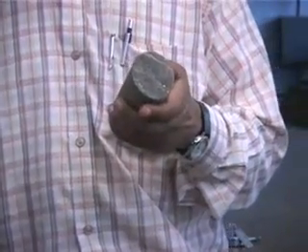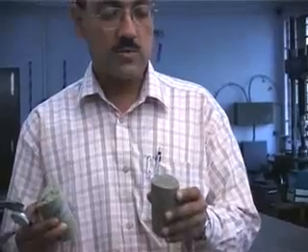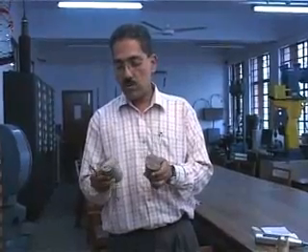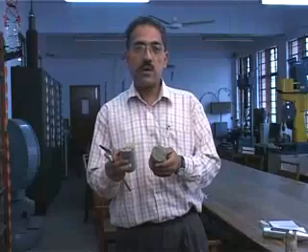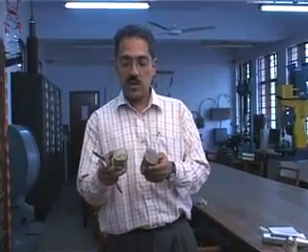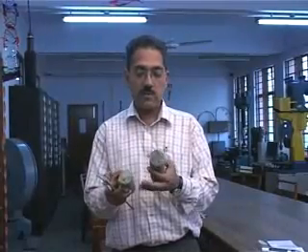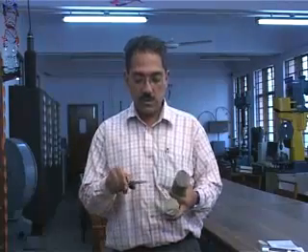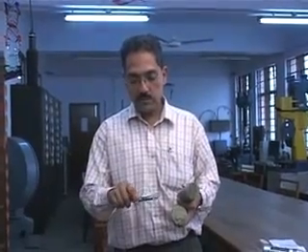So if you recall, the point load index is basically the point load divided by the square of the diameter of the sample. So we need to find out what the diameter is. Although both of these samples were obtained from a drilling investigation using an NX bit, so we know roughly the diameter of the sample will be 55 millimeter, we need to take a careful measurement of the diameter. For that, we are going to use this pair of calipers.